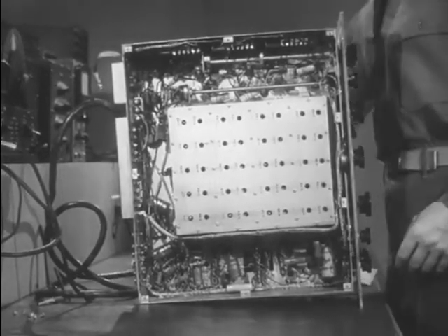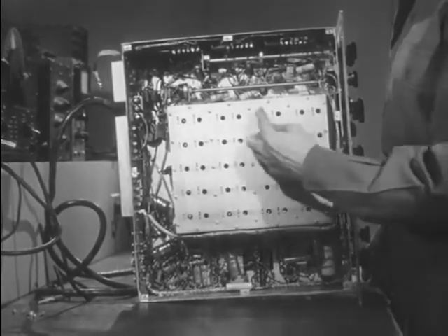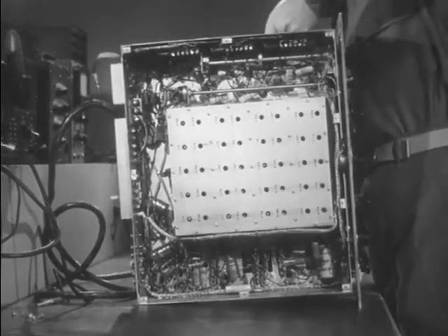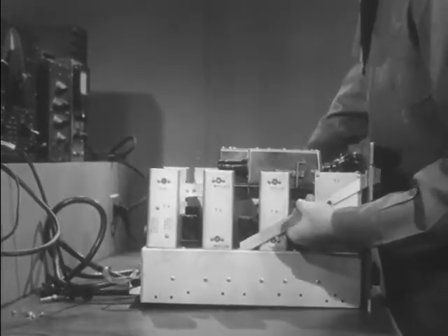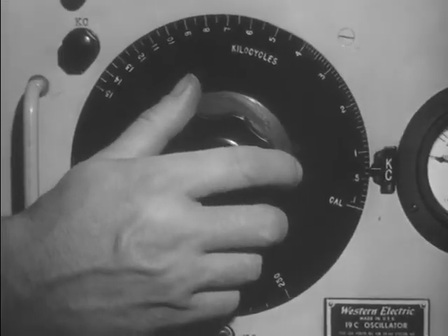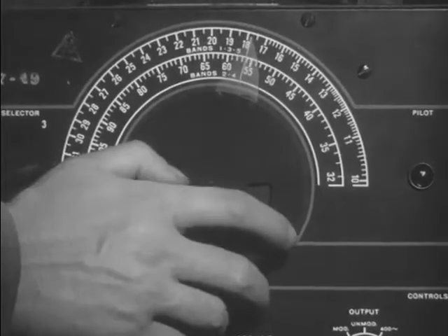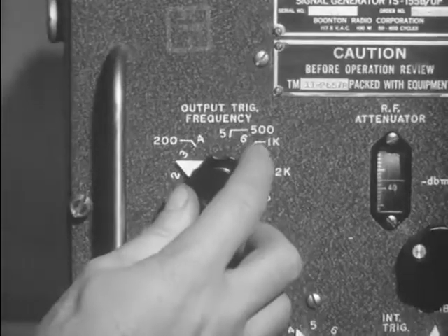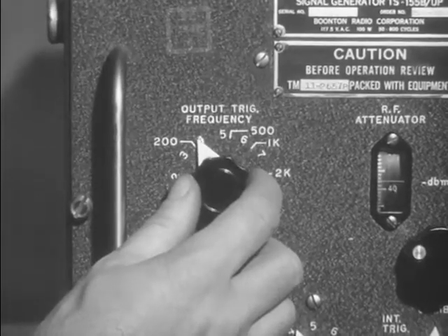The tuned circuits of any receiver must be accurately aligned to operate at maximum efficiency to permit reception of each of the transmitting stations or frequency channels. To test or realign a receiver, signals are needed on several frequencies in order to accurately adjust the circuits of the set. So the signal generator or oscillator is used.